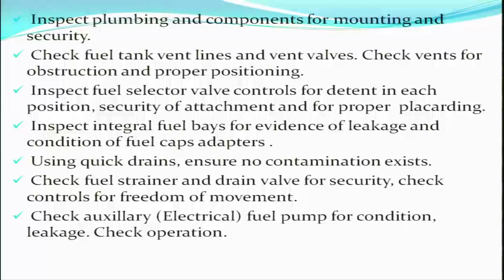As part of the maintenance inspection in 100 hours on the fuel system, we inspect plumbing and components for mounting and security. So all the plumbings, all the components are to be inspected for security, whether they are properly mounted or not. Check fuel tank vent lines and vent valves. The tank vent lines and the vent valves are to be checked. Check vents for obstruction and proper positioning. So vents are to be checked whether they are obstructed or clear and are properly placed, properly positioned.